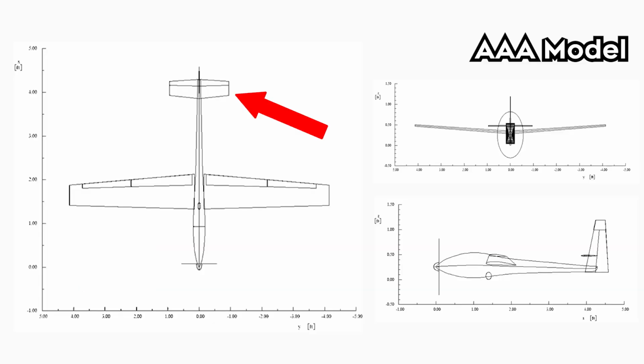So the geometry of the aircraft is that of a conventional glider. It has the conventional glider main platforms, which are a wing, a horizontal tail, and a vertical tail, as seen in this 3 view. The wing is a mid-wing with a slight dihedral, but the important part is it follows conventional glider principles, where it's got a large aspect ratio to reduce drag.